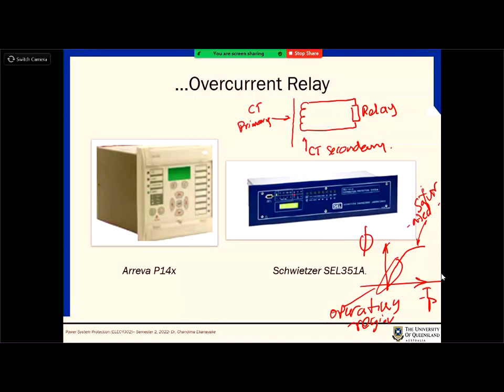Okay, so for that, as I said, these relays should be low impedance. If it is high impedance, then the CT will go into this saturated level. So what happens is that if the relay impedance is large, then the operating characteristic goes to the saturation region, because the relay can't push that much current through that sort of impedance, right?